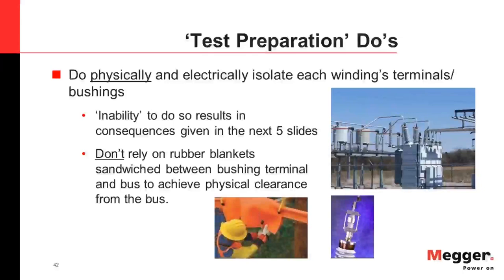So in these cases, sometimes you'll see the use of what's called a lap connector. And I show that in the bottom right-hand corner of the slide, an image of it. What that does is it's there to allow you to practically, more or less, physically disconnect from the power grid when you're in a situation like rigid bus. Basically, you're dropping the two side bars of that, I don't know if I can point to it.